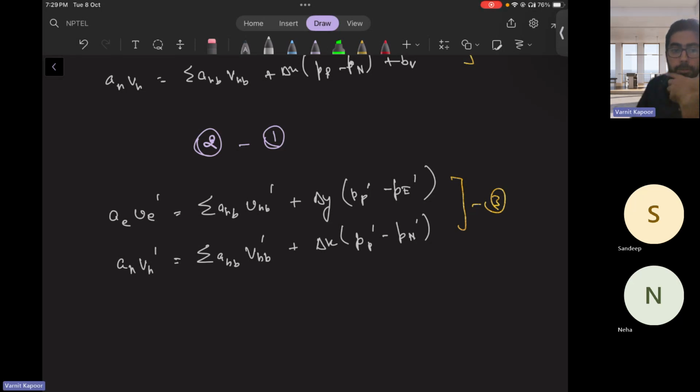As per the SIMPLE algorithm, we need to solve these two systems of linear equations to get the dash values, so that U star and U dash combine to give the actual velocity field, which will satisfy the continuity equation. So here's an approximation in the SIMPLE algorithm. The contribution is coming from dash velocities and dash pressures, the corrected velocities and corrected pressures.